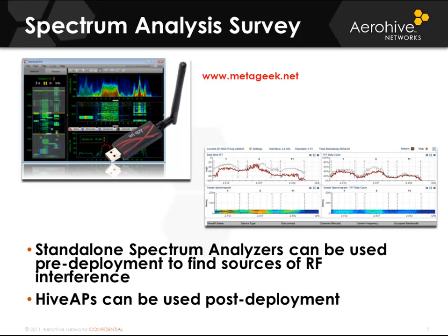Sometimes when you're deploying, you may have to switch your physical spectrum from 2.4 to 5 gigahertz, or from 5 gigahertz to 2.4, or from one channel to another, simply to avoid any layer 1 noise that could be creating a problem. And you are not going to find that simply by doing a layer 2 analysis. Spectrum analysis is vital to a properly deployed Wi-Fi environment.